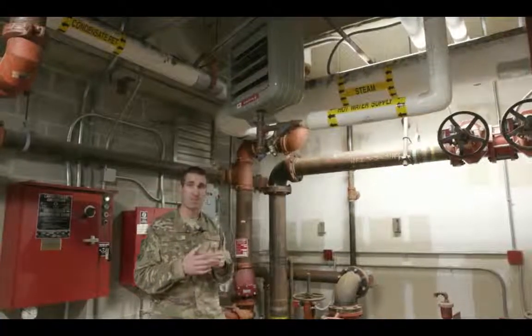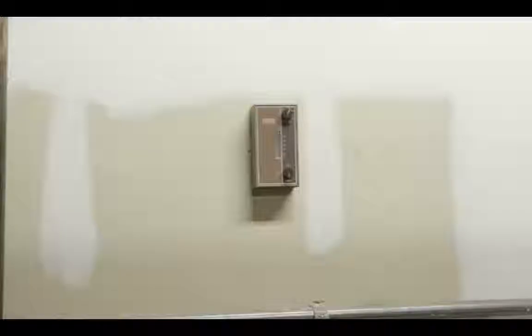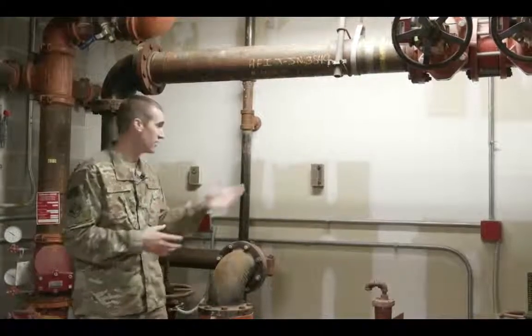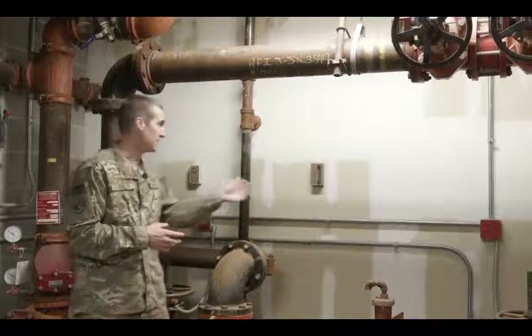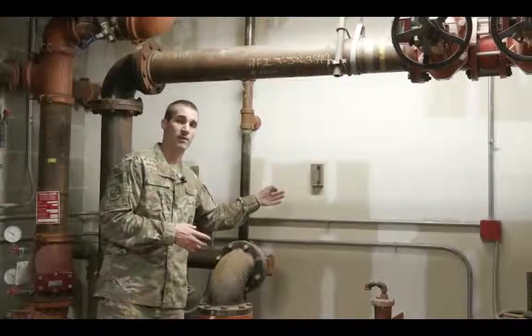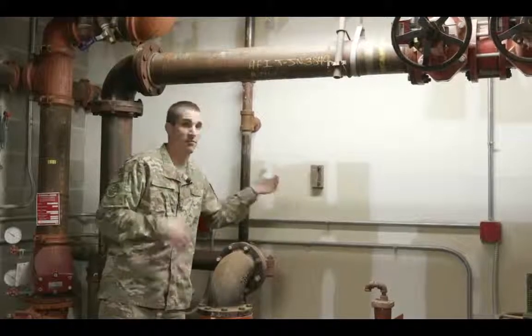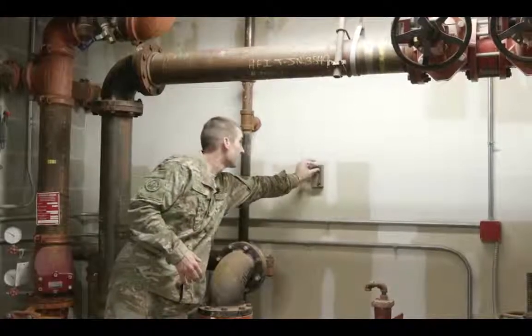Now, the set point can be adjusted over here at the controller. The controller and the sensor in this case are housed together. And what we said before is when you have a sensor and a controller housed together, that's a stat. So this would be an example of a thermostat, with an adjustable dial for the set point. So if I turn up the set point, we would expect that fan to kick on and provide more heat to this space.